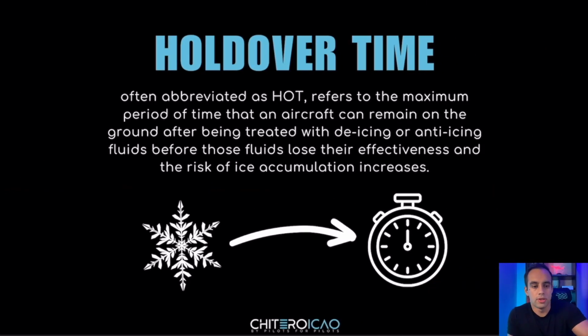Then let's go for the main topic here. This is something that we need to understand, which is the holdover time, right? So it's holdover. It's the time our fluids can hold over, which means that once we de-ice an aircraft or anti-ice an aircraft, that fluid has an expiration time. I might be wrong, but if I'm not mistaken, it's like 60, 90, and 120 minutes. Like 1 hour, 1 hour and a half, and 2 hours, something like that.